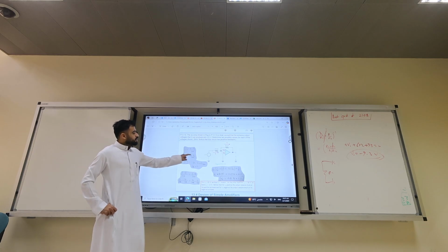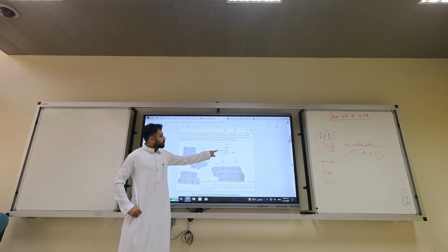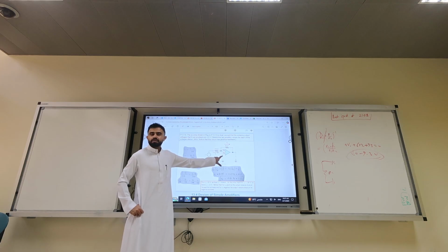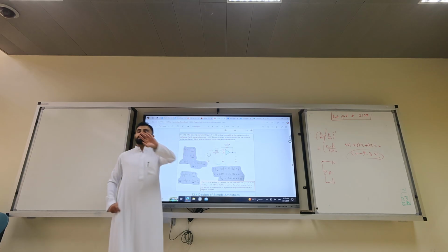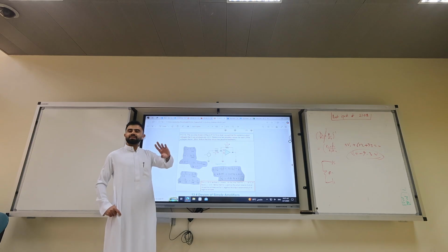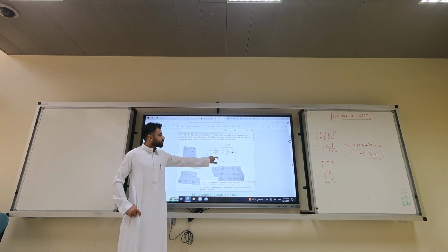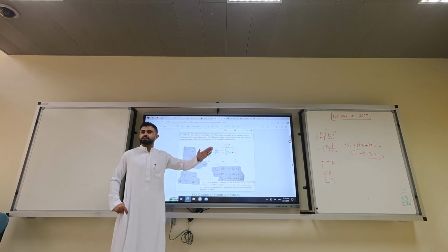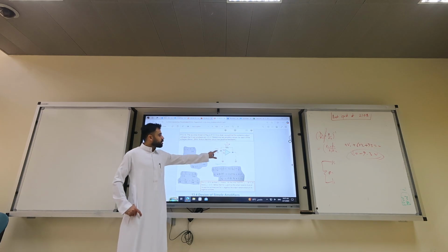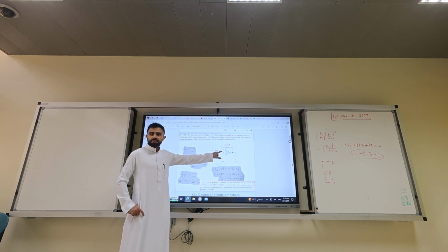What is I1? 2 volt minus Vx. What is Vx? 0. Negative feedback, so it's 0. 2 minus 0 is? Oh no, it's a positive feedback, so this is not a virtual summing point. So V plus and V negative, they are not equal. So we call this Vx.